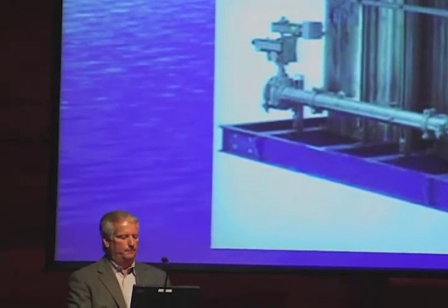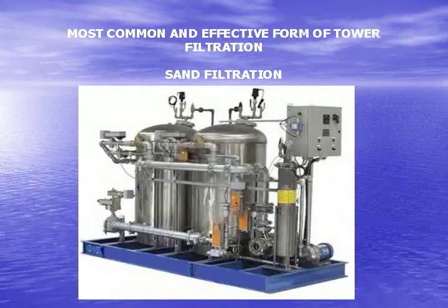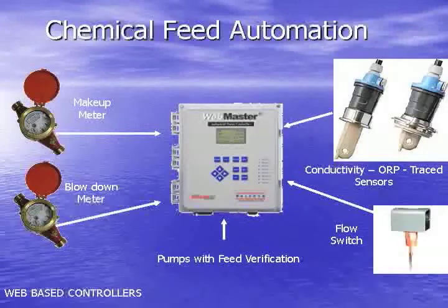The most prominent one is the sand filter units. Okay? And you'll hear more about that a little bit later. The other thing that we have, and probably the best thing that has occurred in the water treatment field in the past 4 or 5 years, is the feed automation. The controllers have really taken a quantum leap in the ability of controlling the chemistry. These meters right now, whether it's a Webmaster, Advantage, or Tracer, or whatever the models you have, now have the ability to do things like conductivity, to blow down, ORP, which is your biocide feed. Some are trace, where they can actually measure the chemical levels themselves and bring it back into the controller.